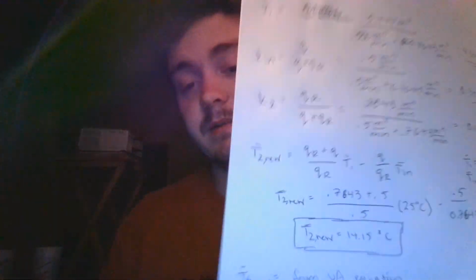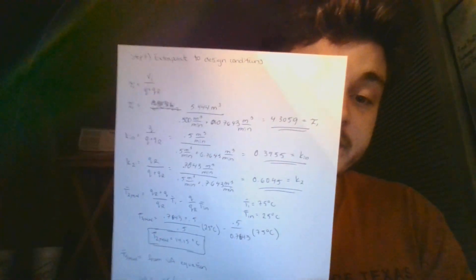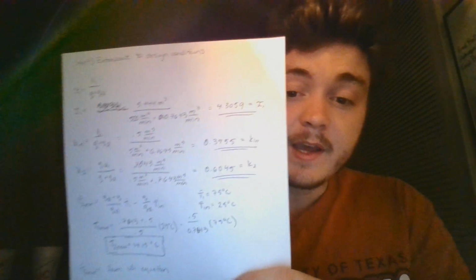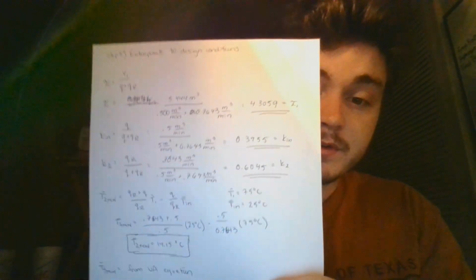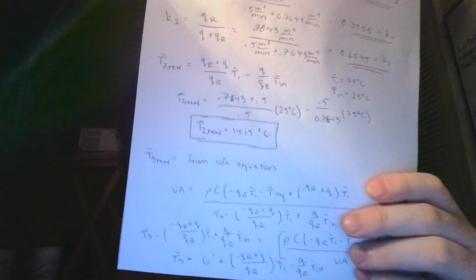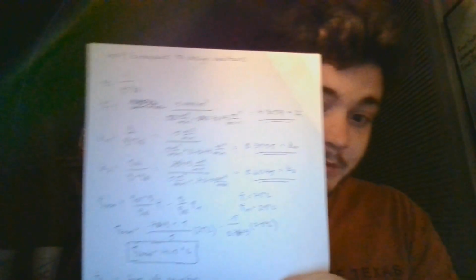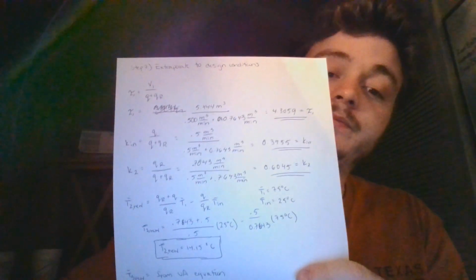This was done by extrapolating the previously found values from the test data, such as QR, V1, V2, or UA. And with this, we were able to solve for new time constants, as well as new gains, and a new steady state temperature for the set point, as well as the temperature in the bottom of the vessel due to the heater.